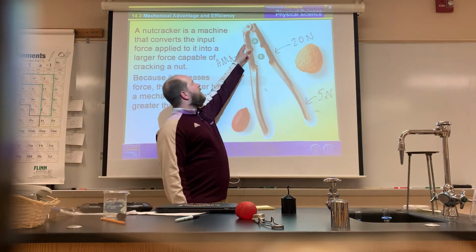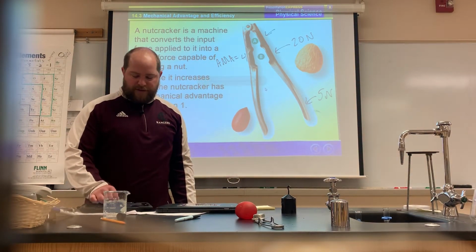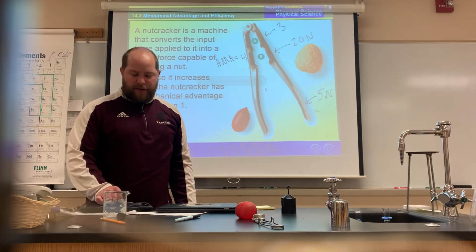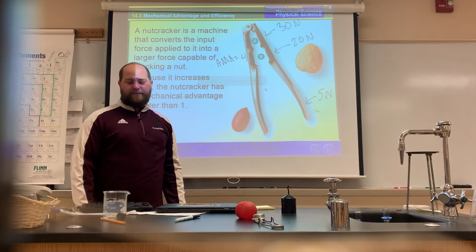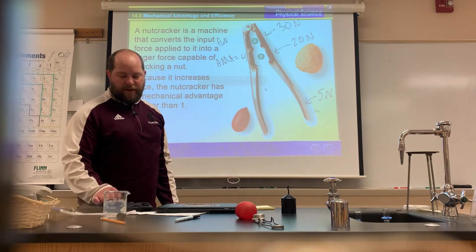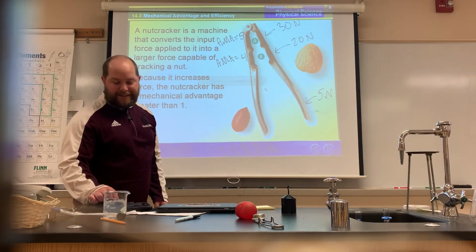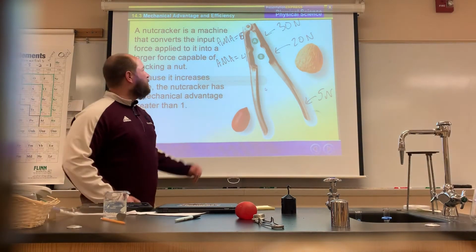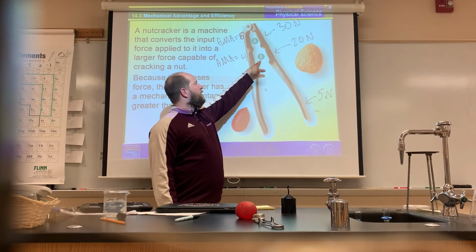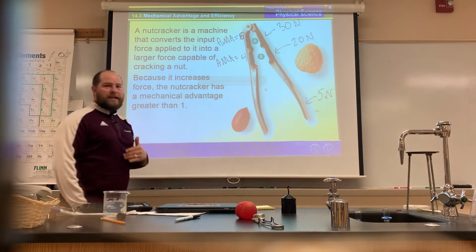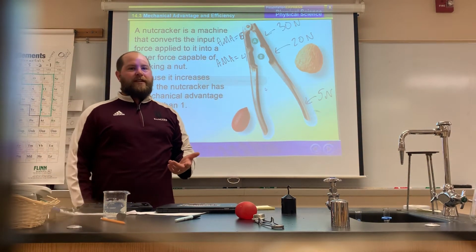Now at point A, you guys probably know how this works. You're going to get a lot more force at point A. So let's just say at point A, you get 30 newtons of force. Then think about, what would the AMA be? Well, hopefully a lot of you guys said it was 6, because it multiplied the force by a factor of 6. All we had to do is put in 5 newtons of force, but then here we're getting 20 newtons, and there we're getting 30. That's the mechanical advantage. And in this section, we're going to calculate the mechanical advantage.